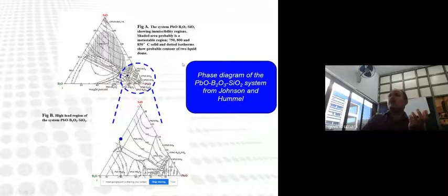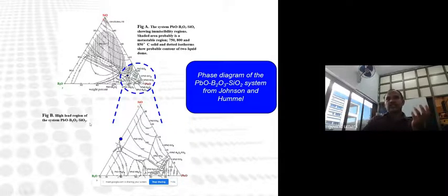So how can we define how much temperature or what firing profile is required? There are some literature surveys where we can see a phase diagram of lead oxide, B2O3, and silicon dioxide. Based on that, we have to select the application, and from that application, we have to find out what melting and glass transition temperature is required, and accordingly select the composition of the 3 ingredients.